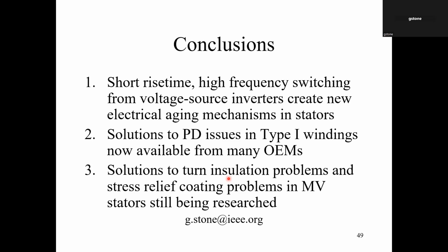There have been solutions for creating PD-free machines for type 1 windings, and they're pretty much available from all the motor OEMs, although they are supposed to prove that those windings are PD-free at a specific impulse voltage plus a safety factor.